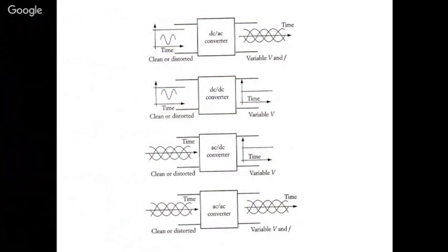Yeah, but actually there again you have to see, the capacitor will act like a short initially once it is on. Then it takes time to charge. And the other thing is, once it is fully charged, it becomes open. At the final stage, it becomes an open circuit.